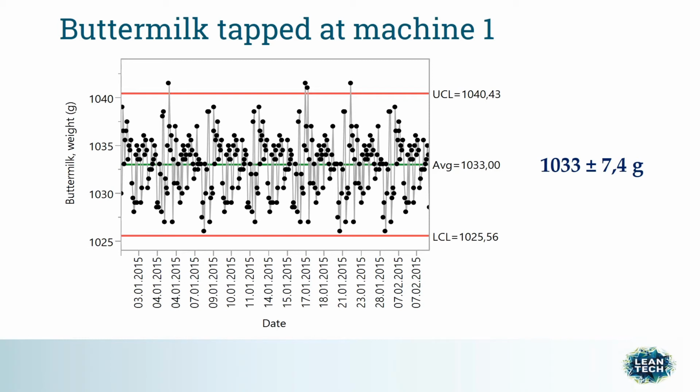You can use statistical process control and control charts for your own process in order to compare different machines or different processes and look at the expected normal variation. And then you can start questioning why there are differences. You can use statistical process control for maintenance purposes. If you have a machine that is starting to wear, you will usually see that the machine is less precise.